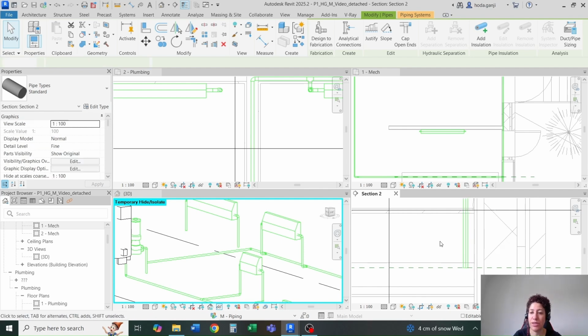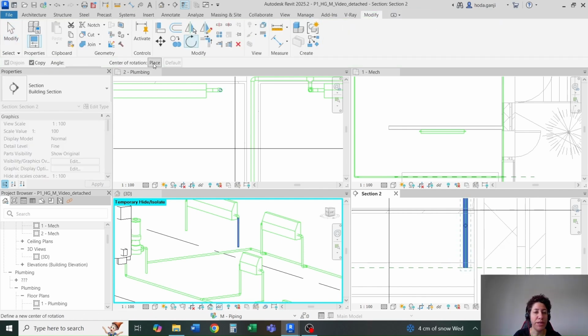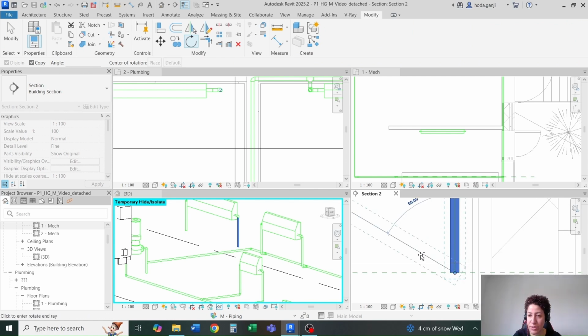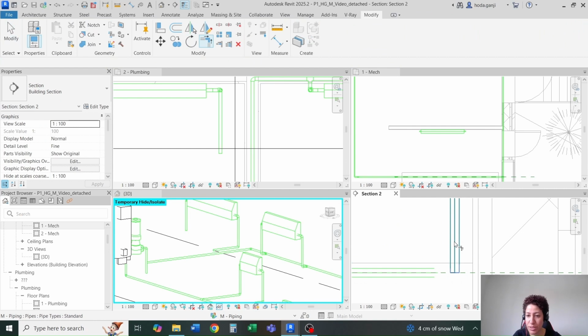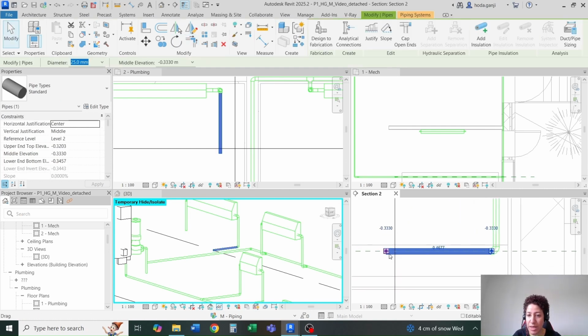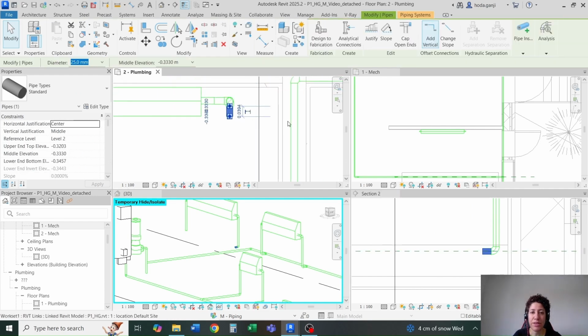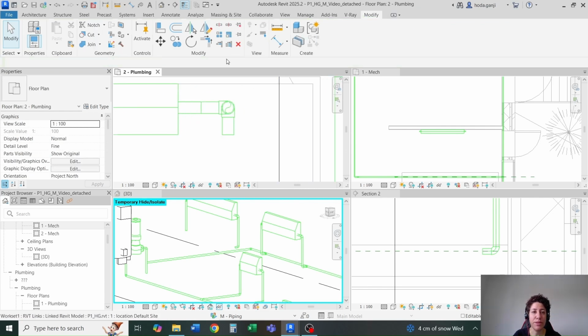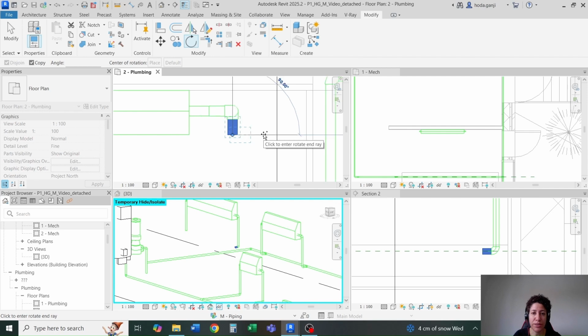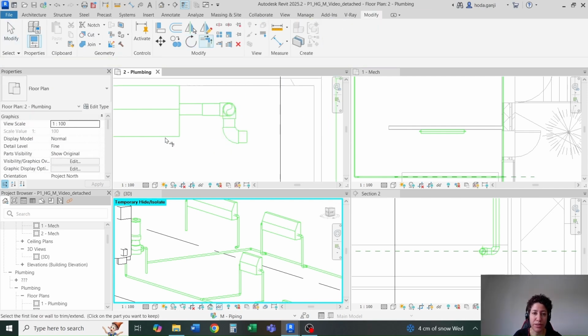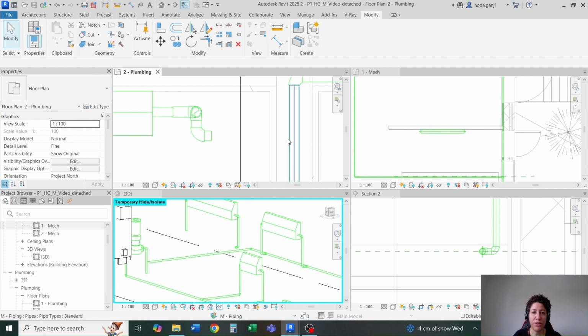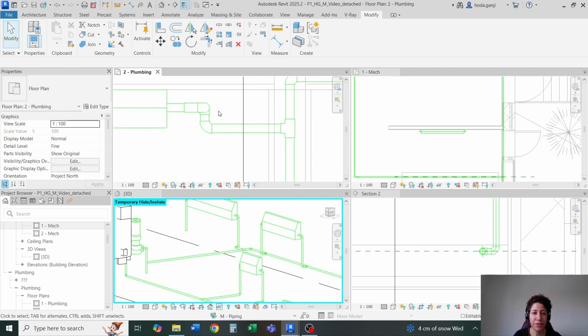So I'm going to rotate it. I'll go with rotate, copy, yes, place. I'm going to rotate it like this. Use TR to have an elbow here and make this a bit shorter. Now this pipe can rotate and get connected to this main one. So I'll go with a rotate in here. Place like this, 90 degrees, use TR, trim the two, and I can just connect this to this one by going with extend. There we go. So this is good.